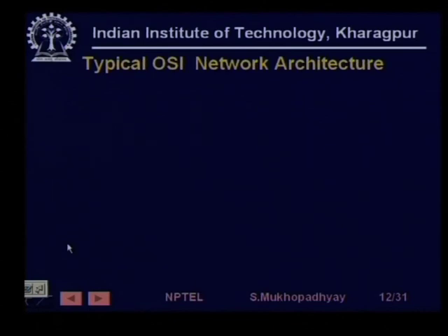So, this gives us an idea of how an industrial network is physically connected. There is a bus which is running all over the factory. This bus may be segmented using repeaters, etc., and then you have to hang devices on these segments, and then they will talk to other devices in that segment or in other segments. You can see that the Fieldbus supports all kinds of devices which are directly connectable on the network or which are not connectable on the network as well.